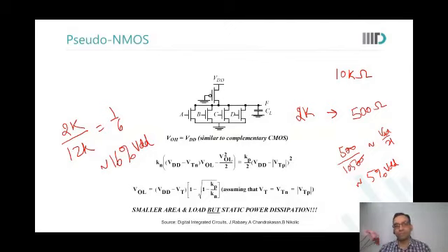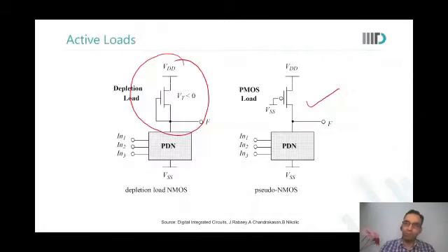Are you able to see this? Yes. But if we know that we are using a pseudo NMOS, then we can design a PMOS also to have that equivalent resistance. How much would you make it? Tell me a value. How much would you want the PMOS resistance to be? Ideally, you would want equal resistance on PMOS and NMOS so that you have almost equal delays for rise and fall. Yes, sir. So I made it very bad. I made it 10K, whereas NMOSs are 2K. So my rise time will be 5 times more than fall time already.